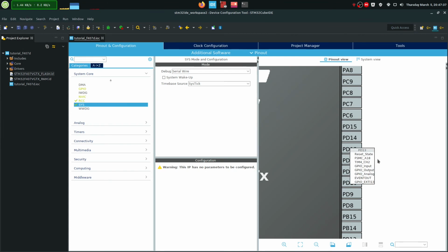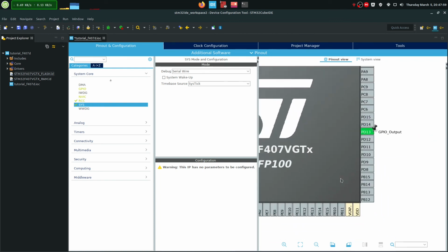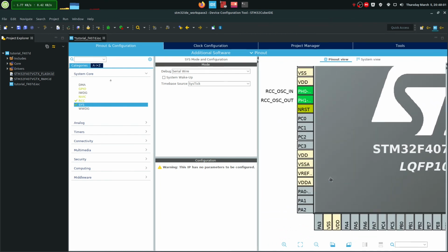And when you click on it, you have multiple options. It's for the peripherals that are connected to this pin, so the analog peripherals inside and digital ones connected to the GPIO peripherals, in this case timers, and basically that's it. And the GPIO. GPIO can do input, output or analog. To drive the LED you have to source current, so GPIO output. So this is that.